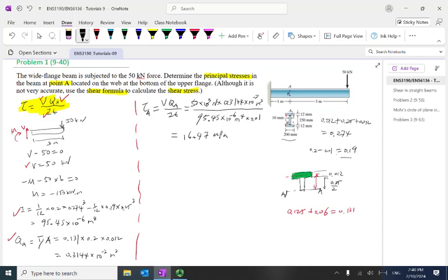So after we know this one, we still should know the tau. Tau will work out. Then we'll work on the sigma. Sigma is on that direction, transverse. Okay, so the sigma A is equal to negative my over r. So we learned this one before. Equal to negative m, we just worked out is negative 150 kilonewton meter.